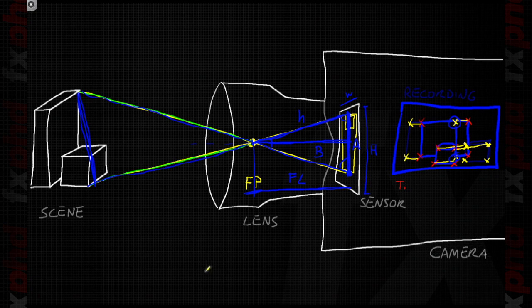But in order for this to work, we need to calculate the triangulation not inside one single frame, but from one frame to another based on the same point. So with that, we can get the differences in the volume, so the parallax. And we are assuming that everything in the scene is steady, and the only thing moving is the camera. Of course, we are going to get elements in the scene that are moving, like people, for instance. We need to rotoscope them out.